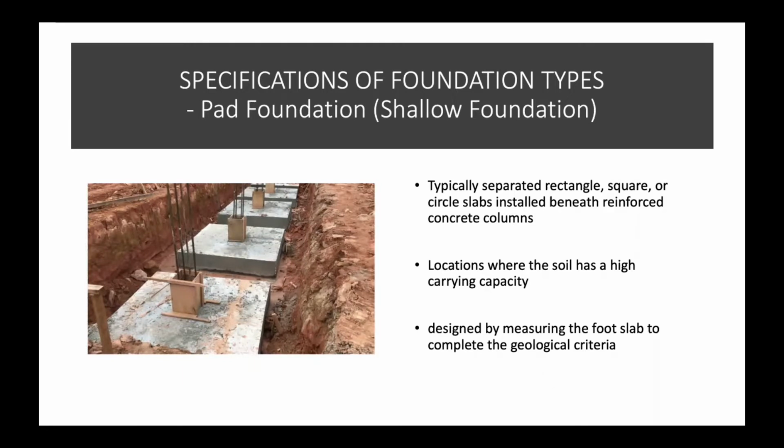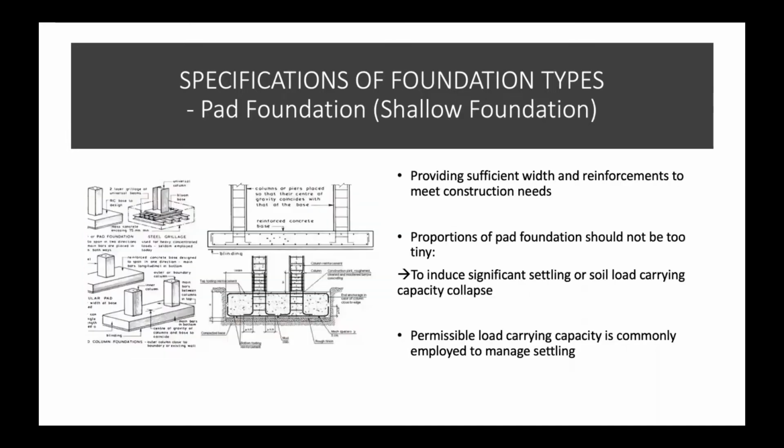It is usually located where the soil has high carrying capacity and is designed by measuring the footing slab to fulfill the geological criteria. The pad foundation also needs sufficient width and reinforcement to meet the construction needs, and it should not be too small, to avoid excessive settling or collapse of the soil's load carrying capacity.